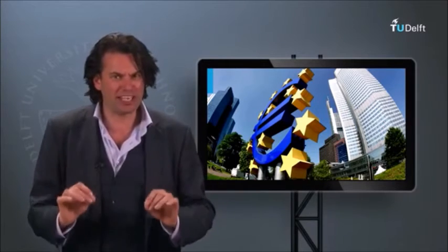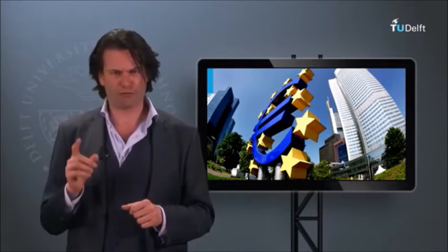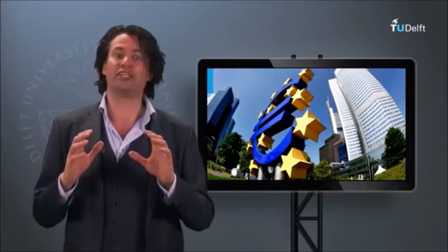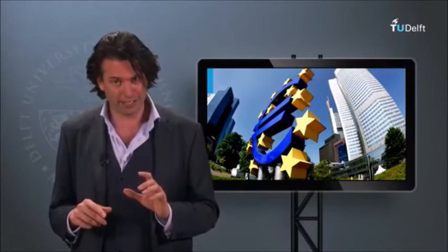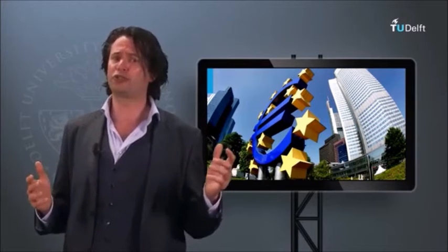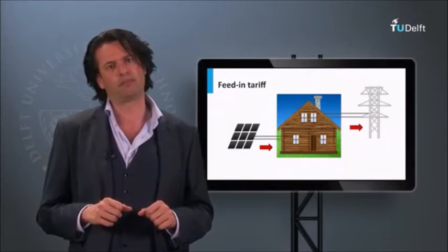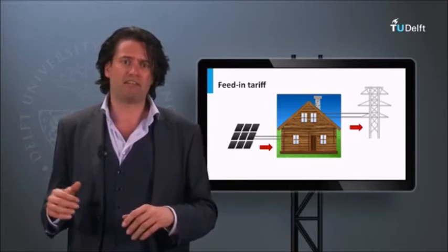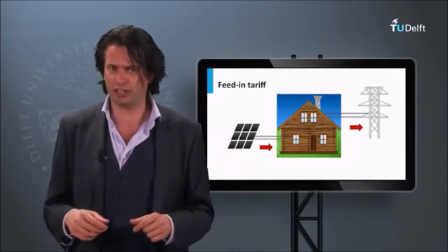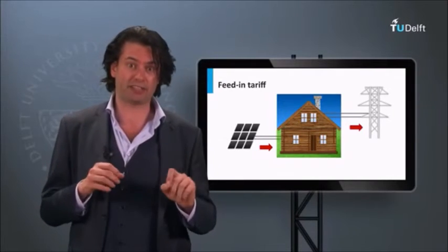Note that this calculation can become more complex as more parameters are factored in. For instance, if you are considering a significant period of time, usually it's a practice to also take into account the time value of money. That is, for example, 1,000 euros today will have a different buying power 10 years from now. Then there are also policy-based factors. For example, subsidies and feed-in tariffs can affect the initial investment and savings. Let us briefly discuss the concept of feed-in tariffs in PV systems.